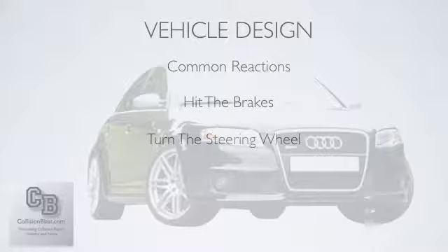So when it hits, it's got that momentum of the front going down and the back going up, and that's why you're going to get the sag. And that's the first type of damage that usually happens, is that sag. The second thing that you're probably going to do, just out of natural reaction, is swerve one way or the other. So you're probably not going to hit them straight on. You're probably going to swerve the wheel just a little bit, and by doing this, it's going to cause the front end to go one way or the other, and that's going to give you side sway.